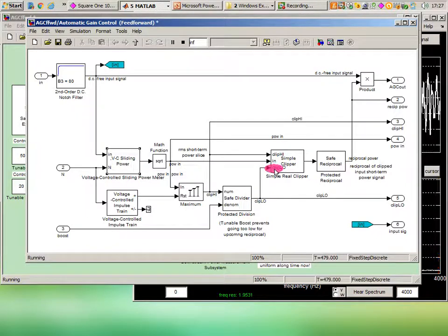So this protects me from going too low. And then of course I reset this, and each 50 samples I've got a new clipping level, and this clips. What happens is I pass on through this clipper everything which is big or bigger than the low clip level. I mustn't go to 0 because here's my 1 over x kind of calculation.